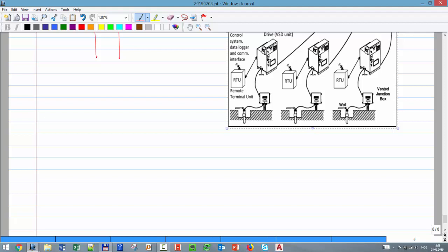Then the fluid comes back in here again, and is directed through this annulus to the next stage. You have a bunch of them, like a pancake, maybe 50, 100 of them. Fluid goes through the annular section, this is rotating, fluid comes out, goes inside here, is redirected again to the center, and then comes out through this part.